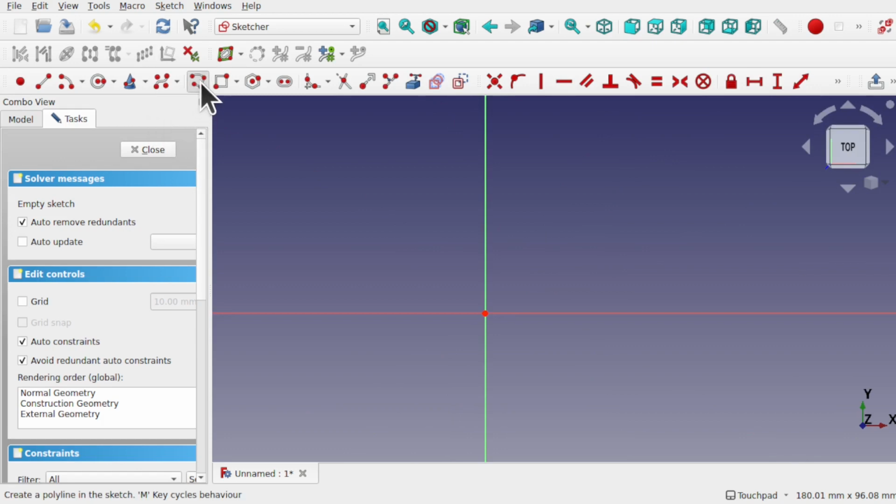So for this, I'm going to use a polyline, and we're looking at the profile, which will be on the side. And basically it's just going to be an L-shape like this. I'm not going to go through constraining. I'm just going to add that in there. I may add some simple constraints like equality constraints, make those equal, and make these two equal.